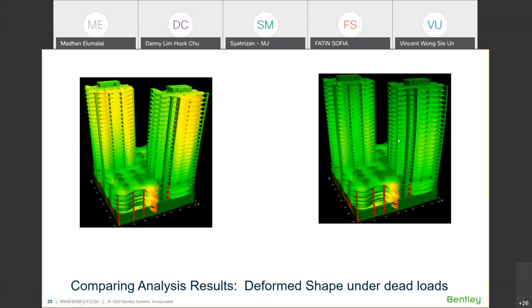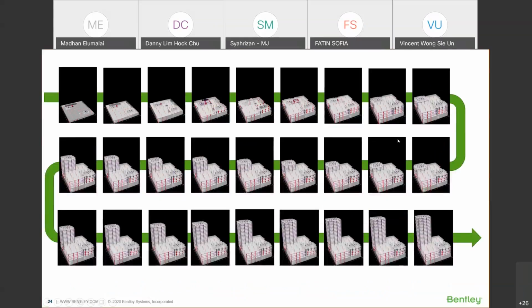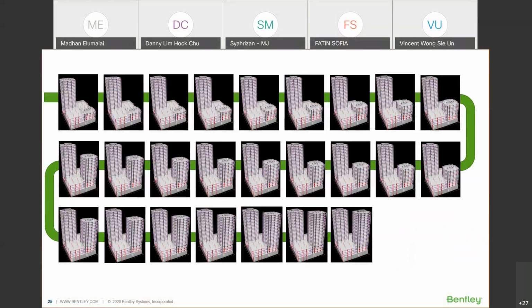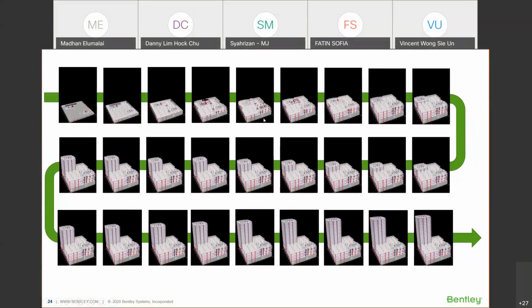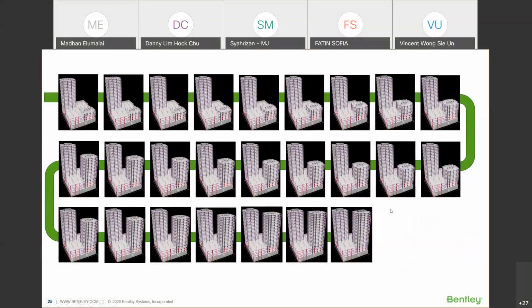Here you can see the same building, at a click of a button, is split into many stages, 27 into 2, combining the basement floors. How many? 1, 2, 3, 4, 5, 9 into 3, 27 plus 27. So it's 54 minus 2, 52 stages, automatically considered by the program. So the program does the analysis for all these 52 stages of this twin-story building, and design. It will be taking the worst case scenario.